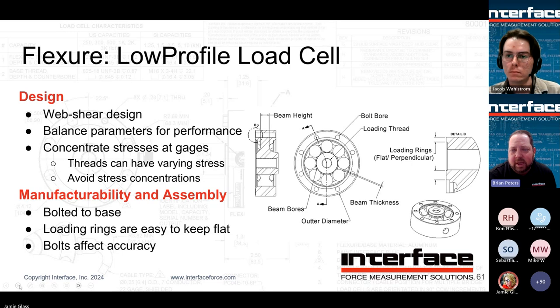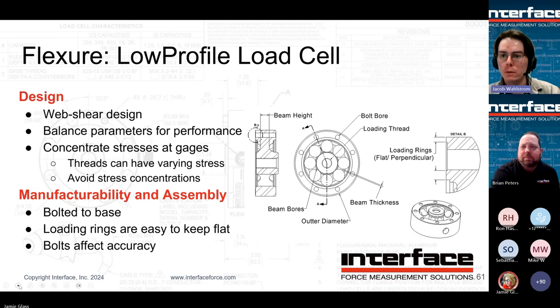So it allows us to have a little more manufacturing flexibility, but then also be able to standardize more on the customer end in terms of integrating with different sensor types or different capacities. So obviously we reach a certain point where we have to grow the diameter, and then we fit another range of capacities within that, and that's all through changing the internal dimensions of the beams. Good point. Thank you, Brian.